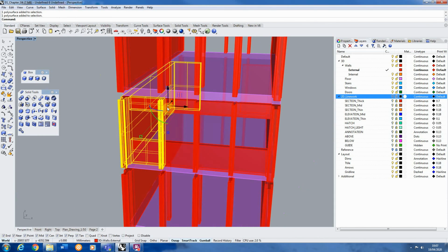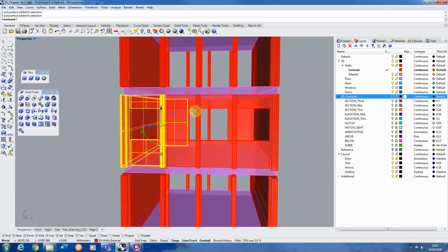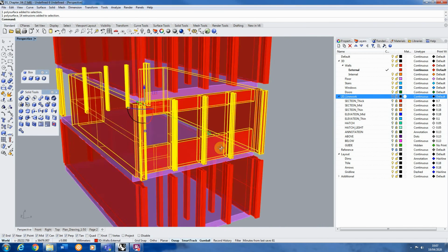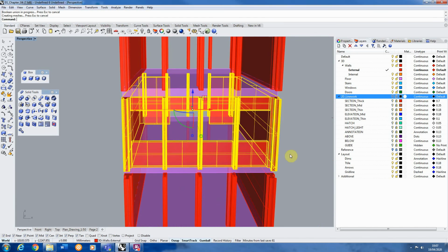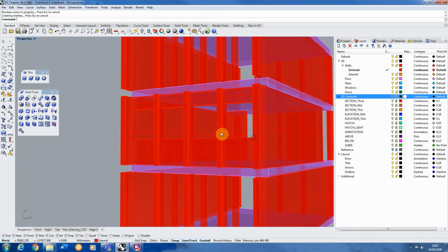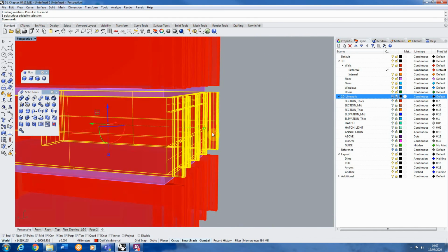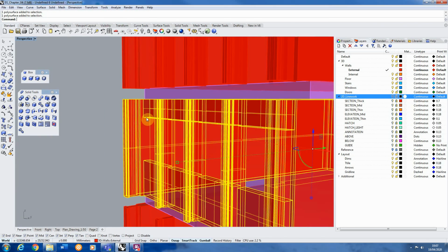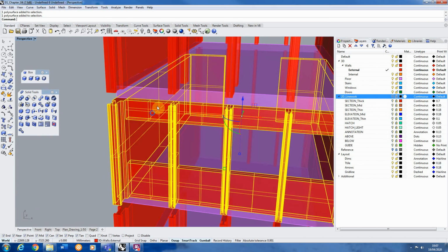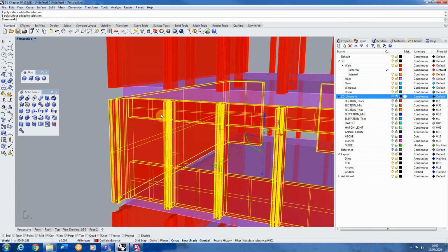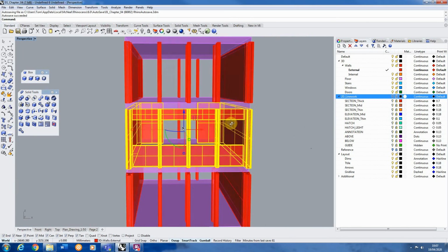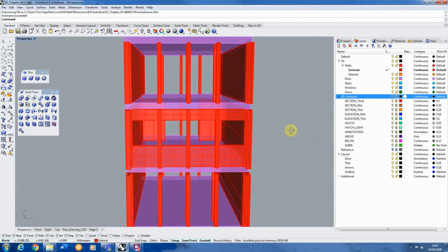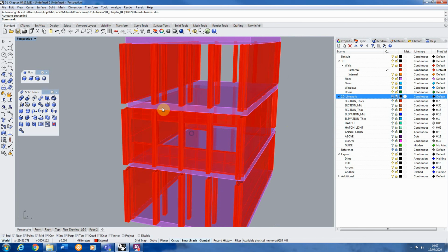And I'm actually going to do that for all these walls here. So all my external walls on this level are unified, like so. And the reason I do this is I just like to keep my models quite neat and tidy, and there's no reason really to have these floating as independent elements, because I can trim them down using other tools later on. So I just quite like to keep everything unified and together as I model and go forward. So that's the Boolean Union tool.